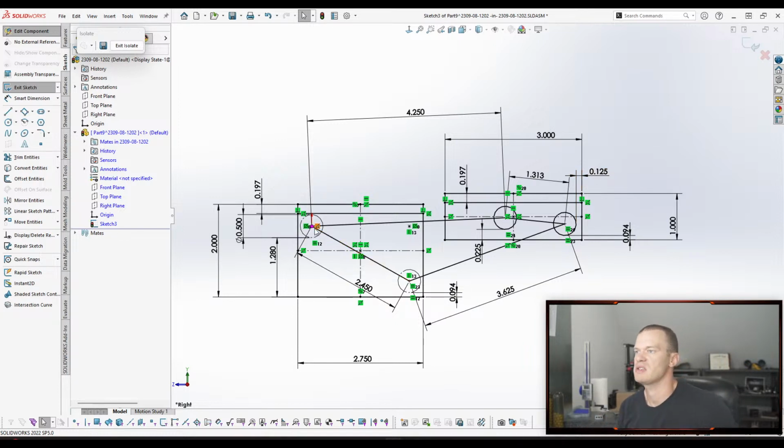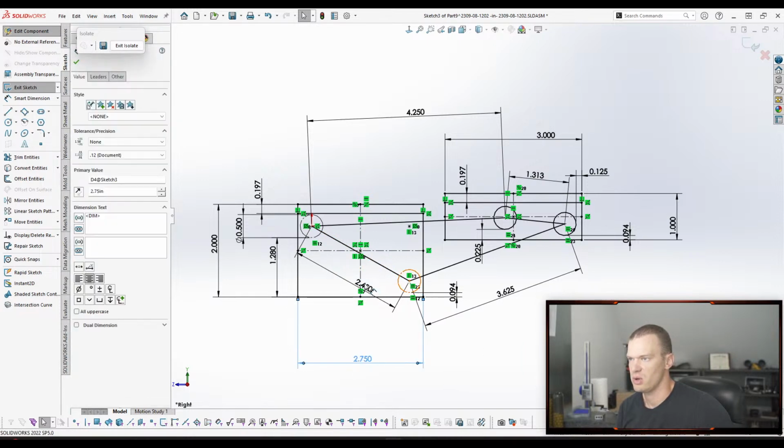Like we talked about last week, we wanted these circles to be symmetric across this plane. So instead of knowing what the distance is and then going in and prescribing some distance, or maybe even creating a dimension here and putting it as half of this dimension using an equation, we just put the center point here, we mirrored the center point across and then made it vertical, right?